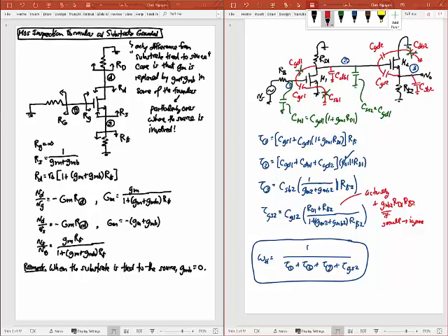None of them? You calculate them all? That's fair. If you have enough time, you can do that. Or if you're not lazy. But if you're lazy like me, okay, CGS1? Yeah, CGS2. Because this last stage here has a gain, not unity, but it's close to unity. And if I have a gain of unity, that means I have very little voltage variation on CGS2. So what I might do is ignore.